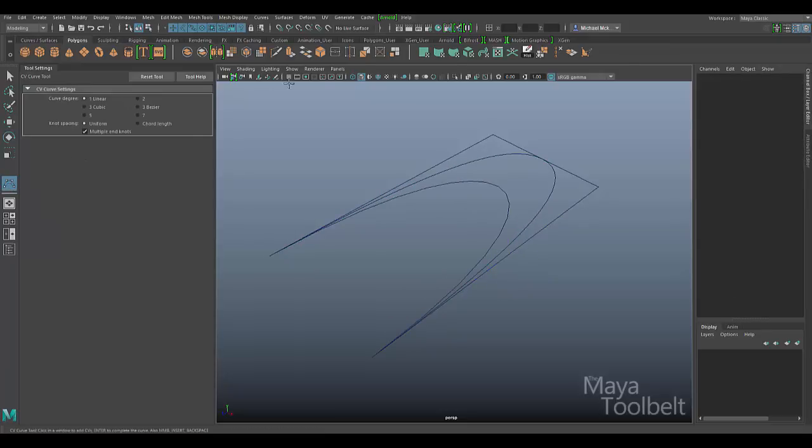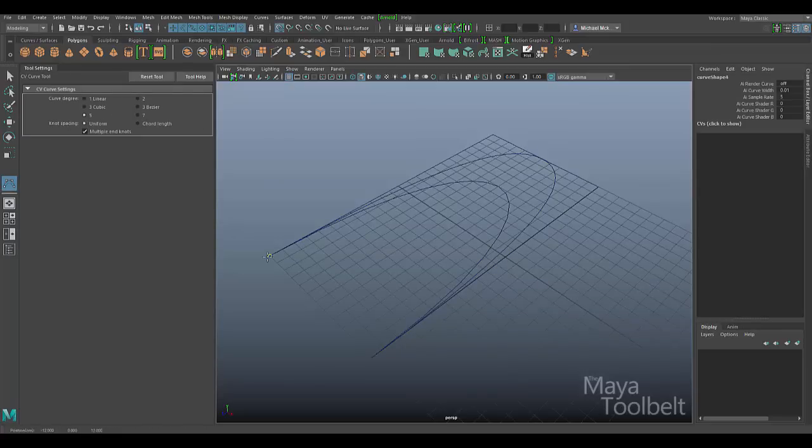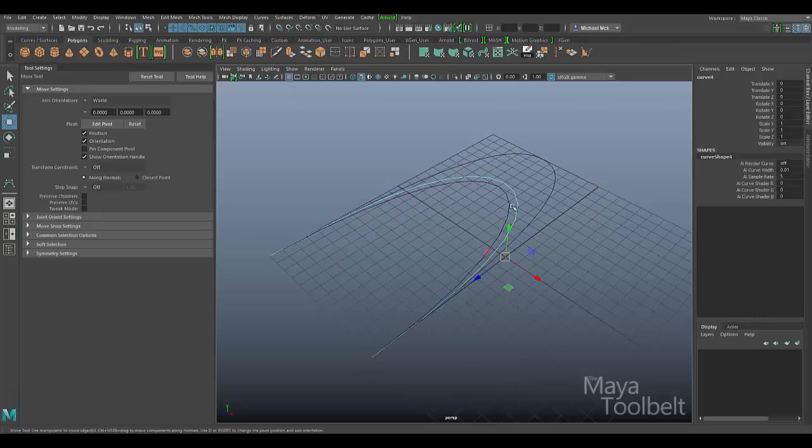And we can keep going. Might as well, since we're here. Let's look at a curve degree of 5. I'll grid snap here. And for a curve degree of 5, I would actually need 6 points. So I'm going to actually point snap here to here. So that's 3 points. 4, 5, 6. Press 3 to smooth it. Hit enter.